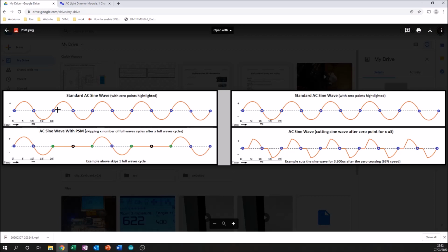Obviously we have 50 full sine waves at 50 Hz, when measuring that against a full second. So we're really interested in the half sine waves, which of course would be 10 milliseconds at 50 Hz. At 60 Hz I believe it's about 83.3, so not 83.3, if we're at 20 here, a half sine wave would be 8.3 milliseconds.